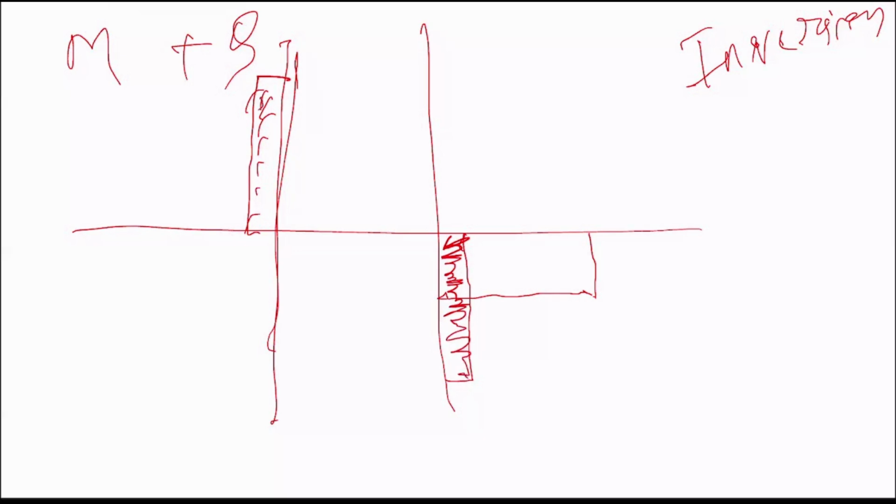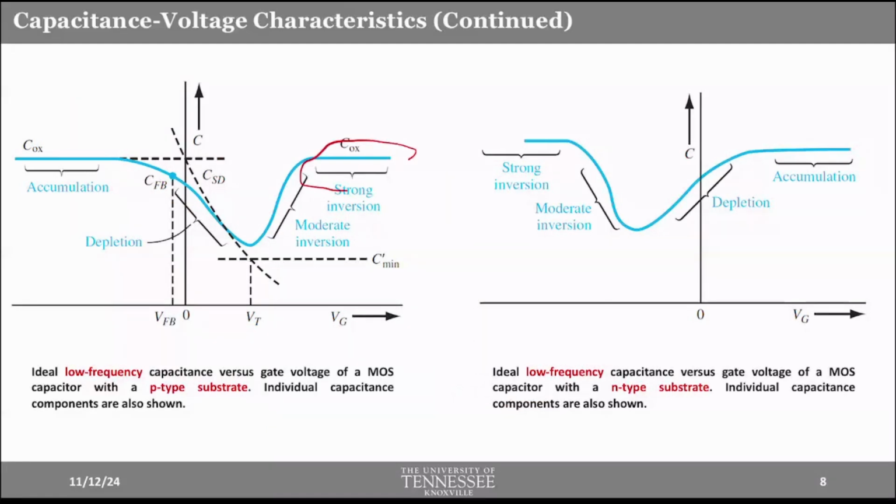Now, if we increase the charge here, this will increase the gathered electrons here as well, right? Do you guys get it? So if we increase the gate positive voltage, the accumulated electrons here will also increase. So this will balance out eventually. For the same reason, you see that at strong inversion it is constant, like in the accumulation region. But interesting things happen in between, when it is neither strong inversion nor accumulation.